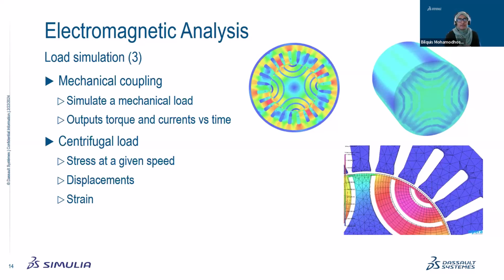You can say that we can redo the geometry, but if you redo the geometry, the very small changes with respect to the displacement will really get lost in the numerical error, if you like. So that's why it's very important to be able to move the mesh and then look at the effect of those displacements on the electromagnetic forces or electromagnetic KPIs in general.